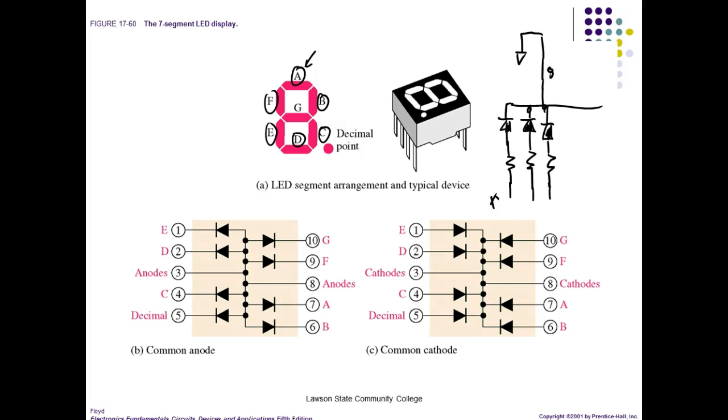Of course, this would be common, right? And then I put a resistor over here, and I put plus 5 volts. If we take for granted that this drops around 2 volts, that means that resistor would have to drop 3, right? So R would be equal to 3 divided by 15 milliamps as a rule of thumb. What size would the resistor be?